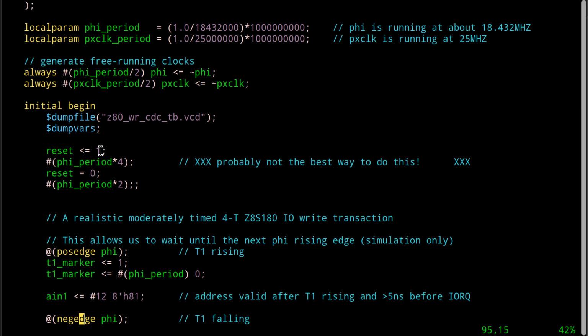This is why you use the non-blocking assignment in synchronous circuits, so that it happens in an orderly fashion. When you do a simulation, you don't have this weird thing where, if this one goes first, then it'll be a 1, but if the other one goes first, it might be a 0. No, that's just bad. And this happens over and over throughout all your code if you don't really think this out.